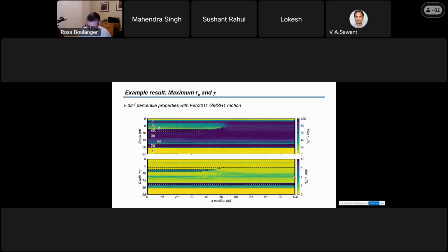Maximum shear strains are similar north and south. So lots of liquefaction north and south. What happens is high pore pressures give you an upward hydraulic gradient, and water flows to the surface. On the south side, that water tries flowing to the surface. It can't get through these silty sand interbeds, and it's easier for it to flow laterally and come up over on the north side of the field. Because water is not flowing upward into the zone, the overlying sands don't get refreshed with inflowing water, and so they never quite generate as high an excess pore pressure and don't trigger 100% pore pressure ratio.